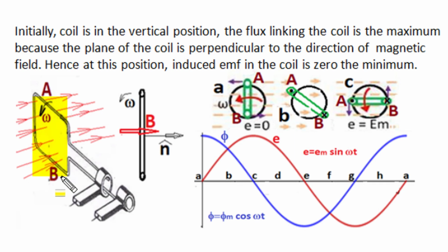Initially, when the rotating coil plane is in vertical position, the magnetic induction vector and area vector are aligned, and this rectangle loop will have maximum flux linkages, and anti-clockwise rotation of the rectangle loop co-sinusoidally decreases magnetic flux linkages with respect to time, as shown by this blue diagram. But induced EMF is not produced only by flux linkages, it is produced by time rate of change of flux linkages, and at position A, instantaneous flux linkages with the rectangle loop is maximum, but the rate of change of that flux linkages is 0.